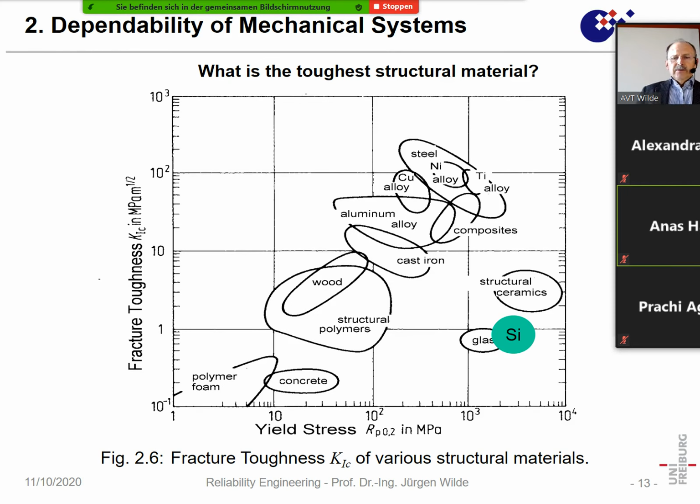And now you could say generally, when the fracture toughness increases, it increases with yield strength. That is mainly for, let's say, some polymers and especially for metals. Yes. So here, typically, all of these are metals. When we look at structural ceramics, for instance, we are here in a range from 1,000 to 10,000 megapascal.